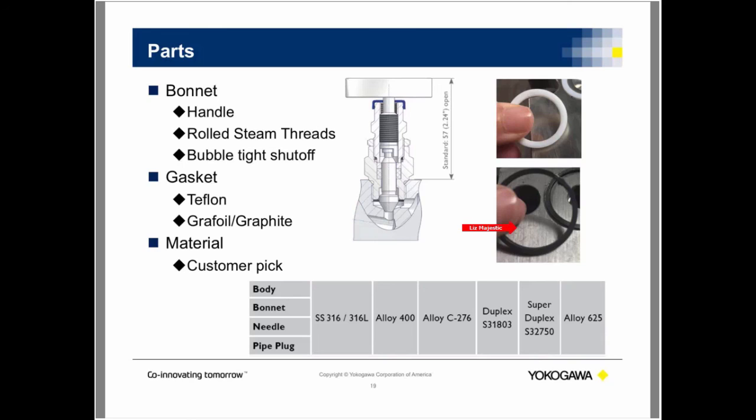Graphite is used in high temperature and vacuum environment pressure applications. They're generally seen in power applications also. They're used in refineries and cogeneration plants also. They seal greatly, but they're super brittle. I don't know if you guys can see this, but over here I pinched the graphite gasket a little too hard, and it actually broke it a little bit. So it shows that it's brittle. It's very, very soft.